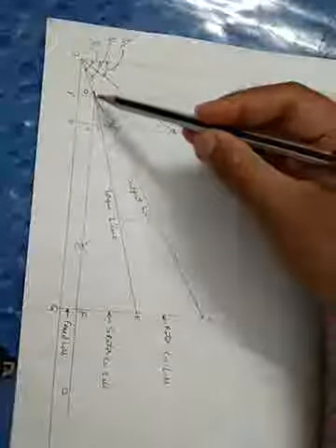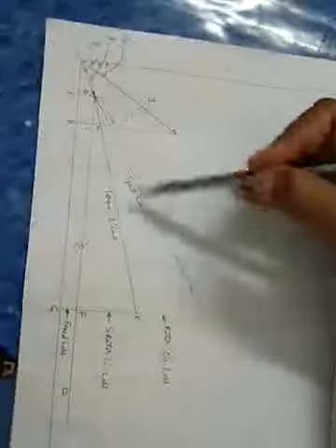The line O dash A is the output line of the motor. It should be noted that the voltage vector is drawn vertically. All vertical distances represent the active or power component of the current.